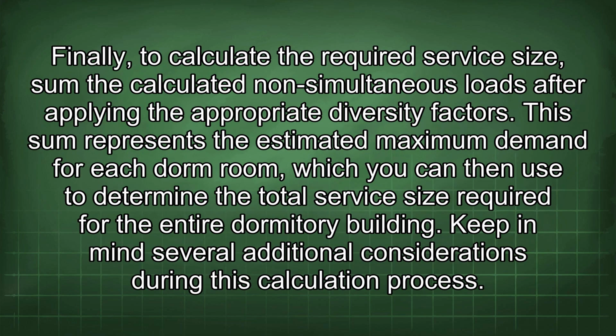Finally, to calculate the required service size, sum the calculated non-simultaneous loads after applying the appropriate diversity factors. This sum represents the estimated maximum demand for each dorm room, which you can then use to determine the total service size required for the entire dormitory building.